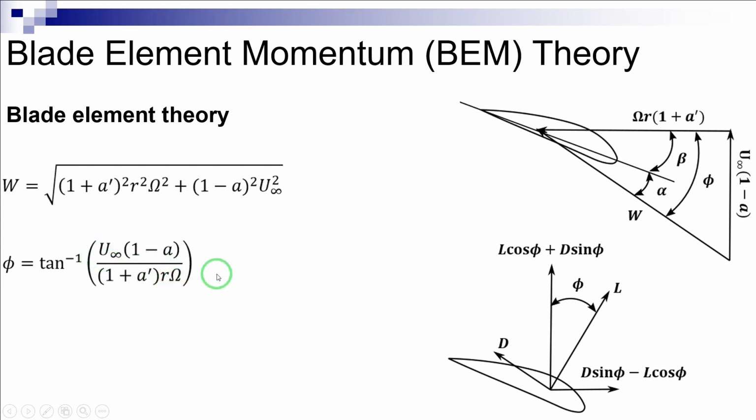This explains why the local blade twist angle in wind turbines is a function of span-wise position along the blade. It is largest close to the blade root while smallest at the blade tip. The reason behind this variation of twist angle is to make sure that the lift coefficients related to the blade elements are held constant and close to their maximum value everywhere, which minimizes the drag at operating condition. The angle of attack is estimated using this equation, alpha equals phi minus beta.